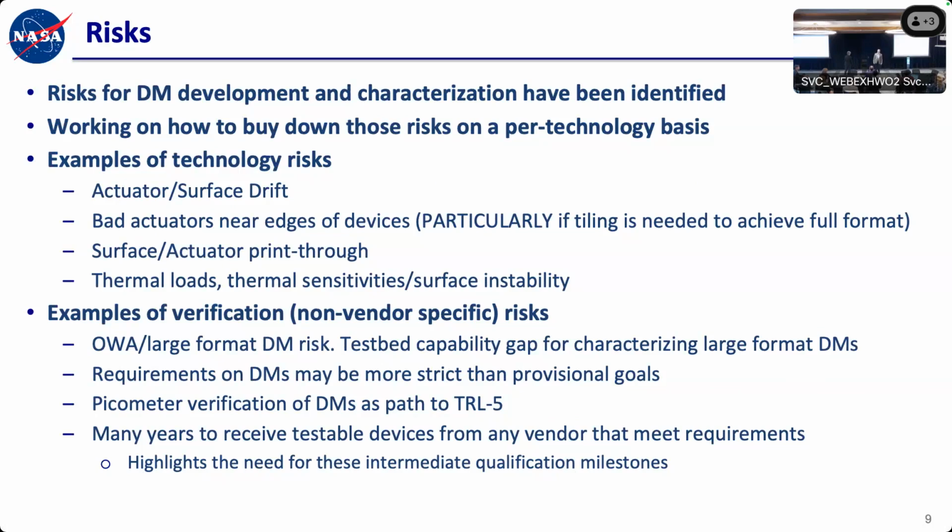So as part of your effort, have you looked at using the DM for doing feed-forward compensation? Yeah, and that actually is what I was alluding to with the low order work, like the low order DM, so that there's some interesting device quirks. These things, they all have their funny little quirks. One of the things is some of the devices have some drift after you apply voltage. And so you don't want to feed forward things from external telemetry because you want the DM to sit still. And then there's also, with pretty much all of them, a state dependent gain. So it's in theory possible to deal with this, but it's really hard to.